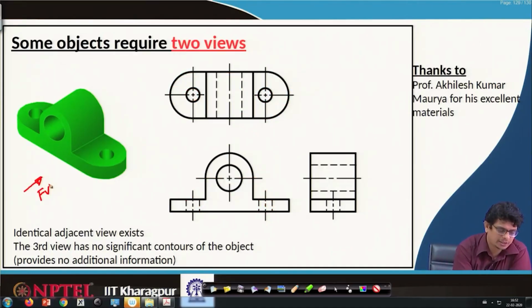This is the front view direction. Let us look from side view. When we are looking at side view, this entire thing turns out to be a simple rectangular block. So, that simple rectangular block on the projection, we are representing it here, and hole begins there, ends there. So, we have that dash lines here, axis pass through that.